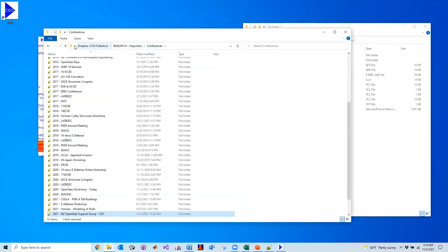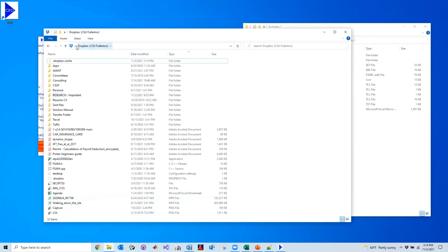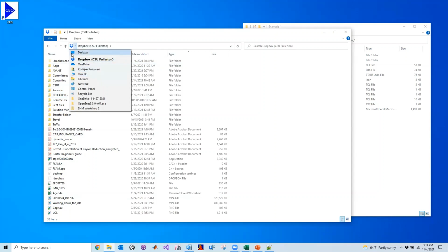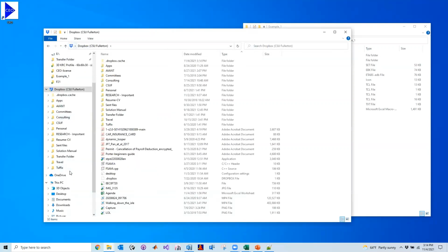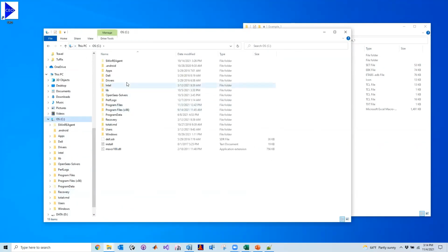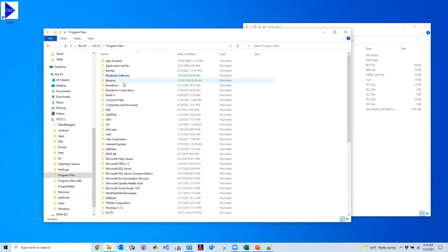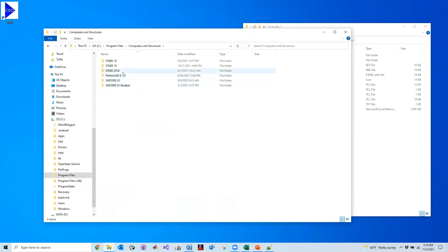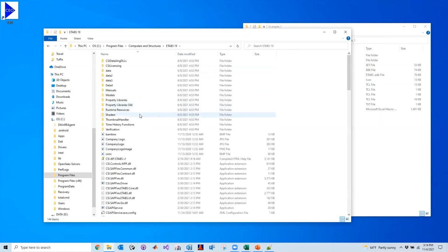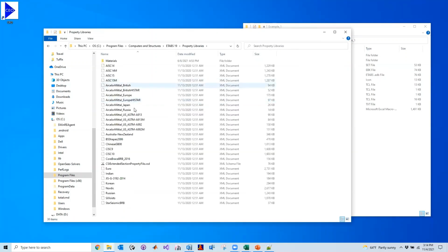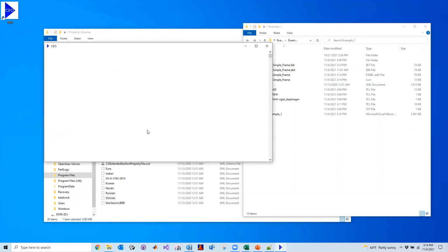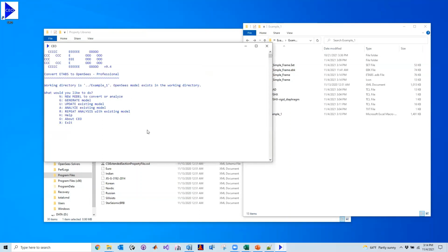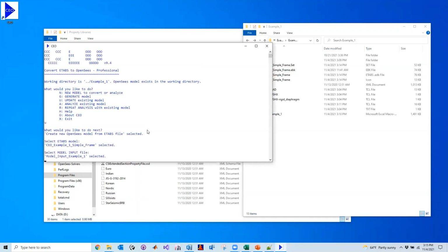You just have to go and copy the one from, hold on, the navigation pane. So you go to program files, right? You go to where ETABS stores all their stuff. You go to the libraries, and here you take the Chinese one, right? All you need to do is copy it inside of its model, and then it will basically do it automatically. So let's say I want to update the model now.